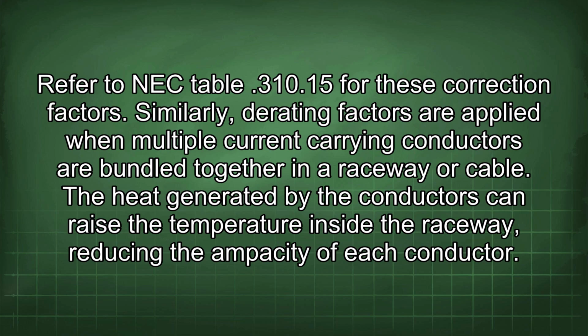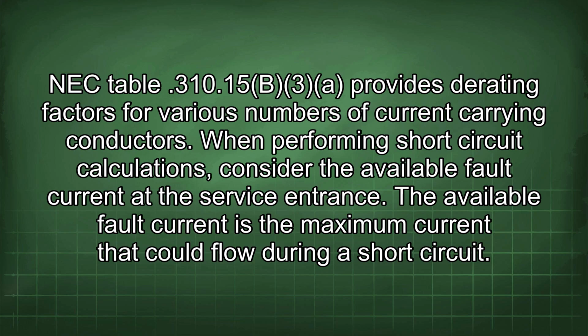Similarly, derating factors are applied when multiple current-carrying conductors are bundled together in a raceway or cable. The heat generated by the conductors can raise the temperature inside a raceway, reducing the ampacity of each conductor. NEC Table 310.15(B)(3) provides derating factors for various numbers of current-carrying conductors.